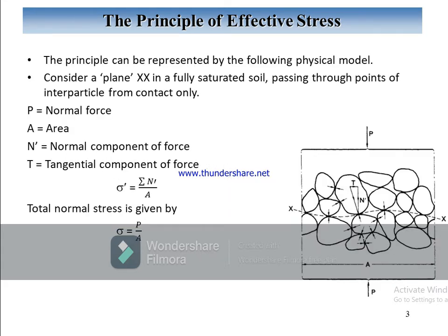Now we come toward a general physical model. The principle can be represented by the following physical model. Consider a plane x-x in a fully saturated soil passing through points of interparticle contact only, as shown in the figure.